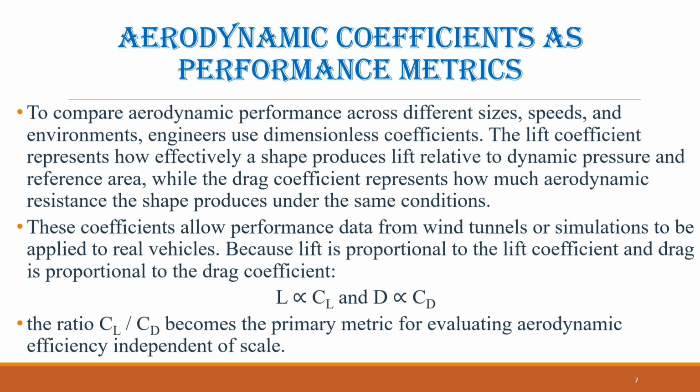Aerodynamic coefficients as performance metrics. To compare aerodynamic performance across different sizes, speeds, and environments, engineers use dimensionless coefficients. The lift coefficient represents how effectively a shape produces lift relative to dynamic pressure and reference area, while the drag coefficient represents how much aerodynamic resistance the shape produces under the same conditions. These coefficients allow performance data from wind tunnels or simulations to be applied to real vehicles.